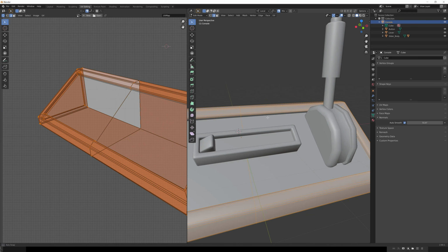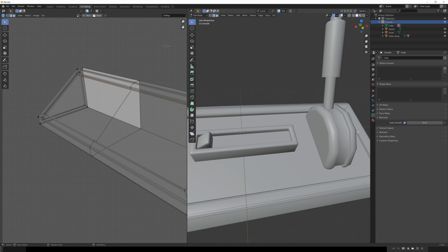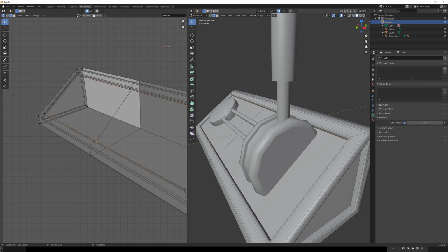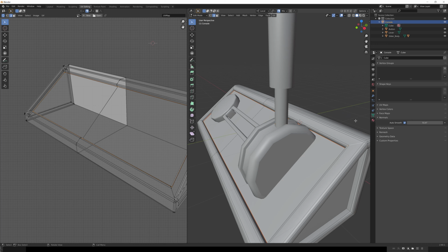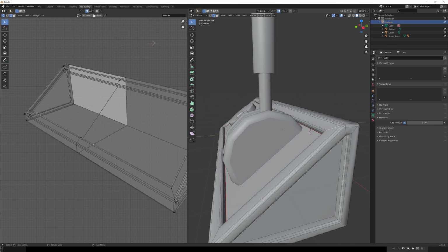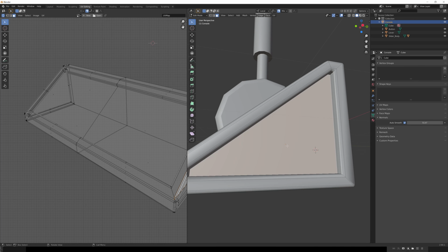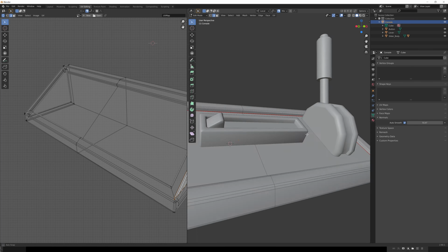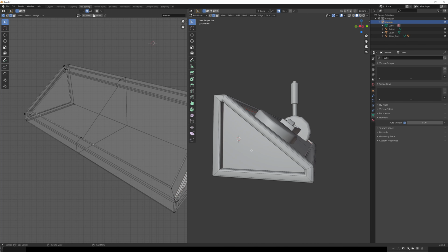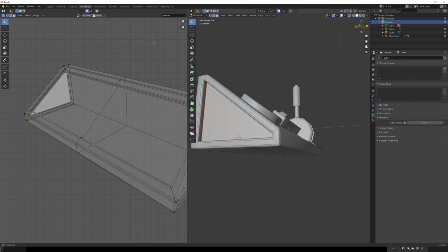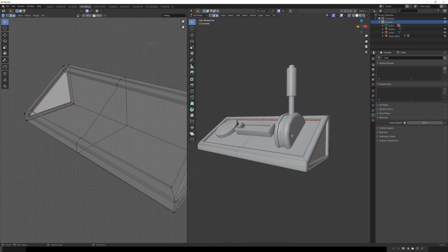I'm going to select a seam, I'd say around the central area in here. It's kind of what I'm interested in. And let's do that one right there. Right click and mark a seam. And then we might want a seam coming out from this edge or not. We will definitely want one here. So I'm going to hit 3, grab this face, hit 2, right click, mark as a seam, and then we'll go to the other side, 3, click, right click, or hit 2 to go back to edges, right click, and do a mark as seam. And that will get rid of those and that central face.